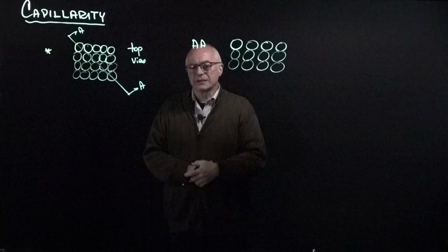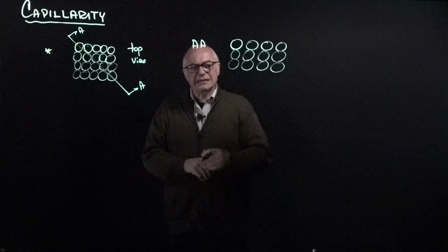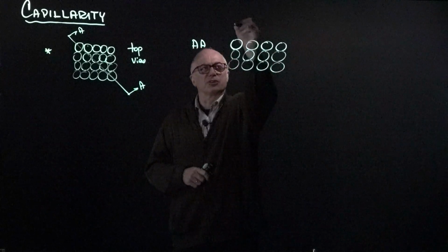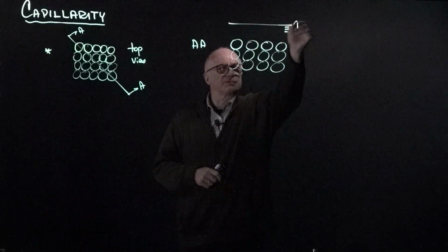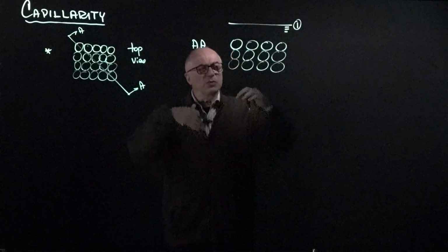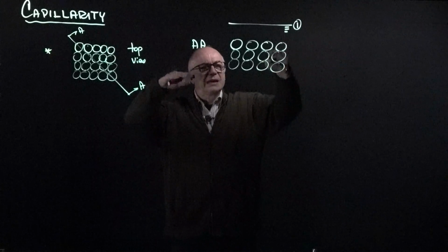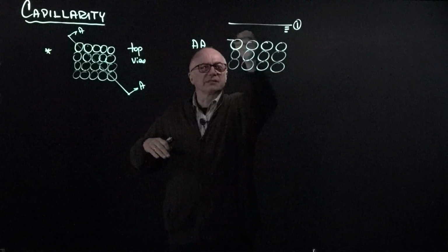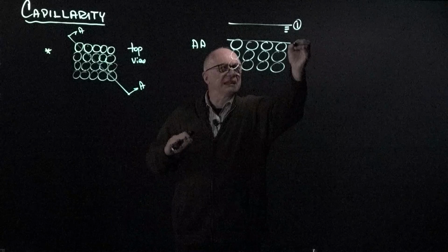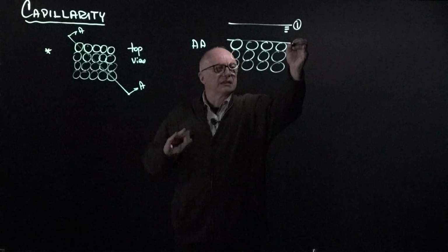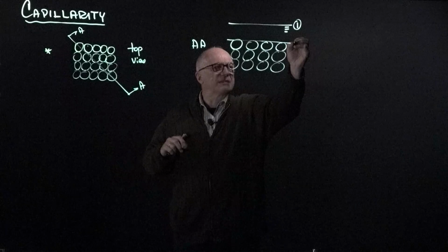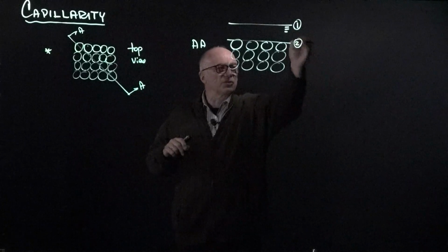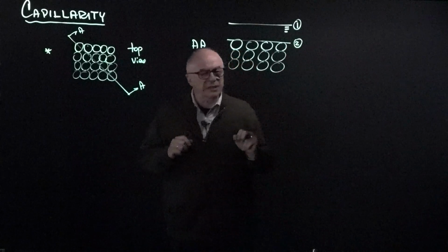And now, let's put water. Let's say that at the beginning, this was totally submerged. Case 1, condition 1, this was submerged. Condition 2, the water begins to evaporate and eventually reaches the surface. And at this point, really, nothing has changed. The effective stress, everything remains absolutely the same, so this is condition 2. But thereafter, the story gets more interesting.